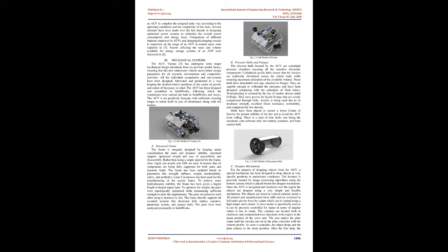A. Structural frame. The frame is uniquely designed by keeping under consideration the static and dynamic stability, structural support, optimized weight, and ease of accessibility and disassembly. Rather than using a single material for the frame, clear virgin cast acrylic and ABS are used. It ensures that all components are being fully supported for both static and dynamic loads.